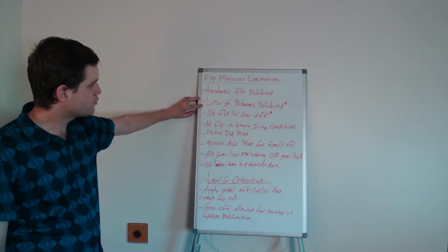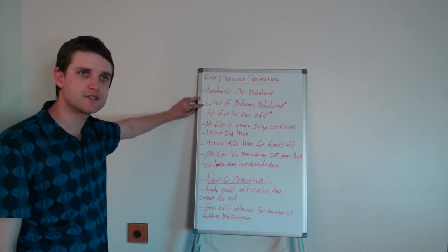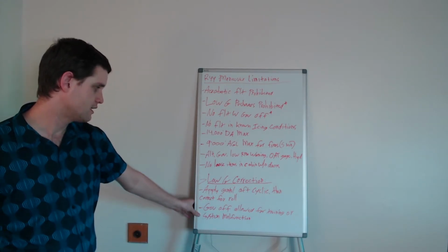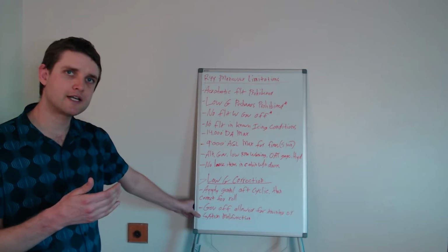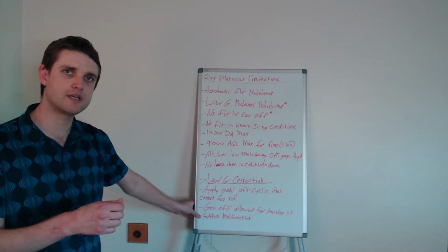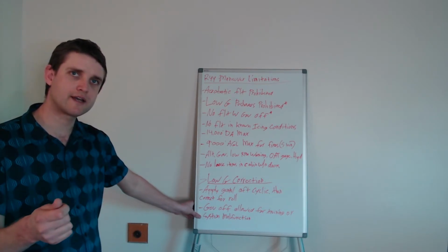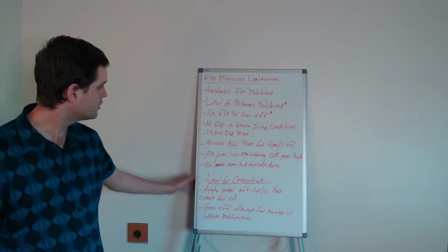And the correction for a low G condition, if you do a pushover and end up in that position, would be to first correct by pulling aft cyclic to get a positive G loading on the rotor system, and the second step would be to correct for the roll of the helicopter with sideward cyclic, counteract that roll and get it back in normal flight.